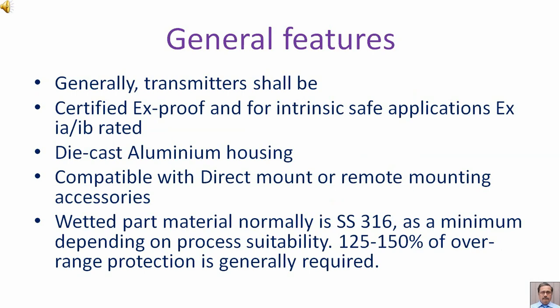Generally, transmitters shall be certified explosion proof and for intrinsic safe applications, explosion IA/IB rated. Die cast aluminum housing compatible with direct mount or remote mounting accessories.